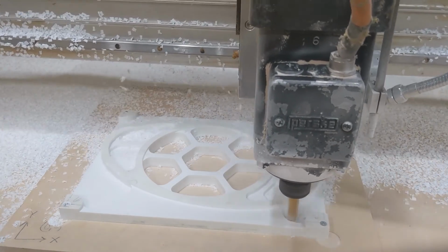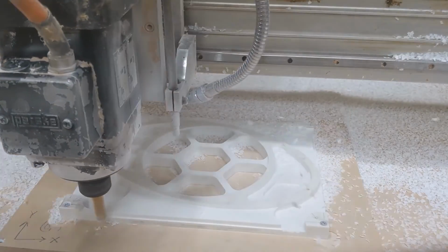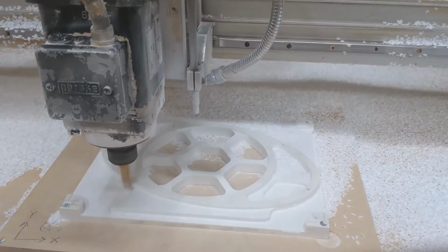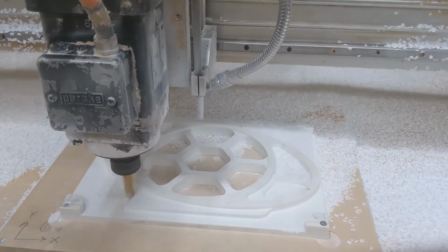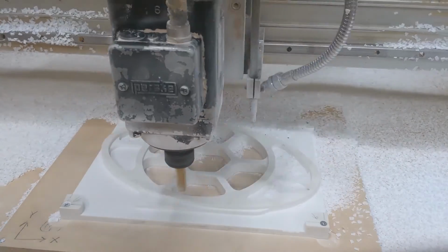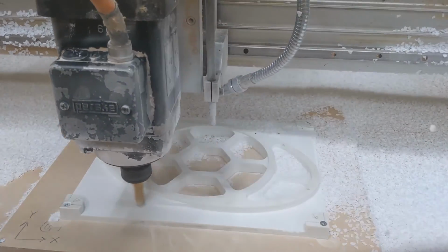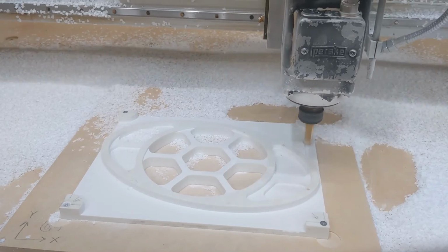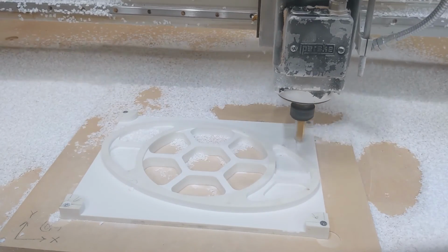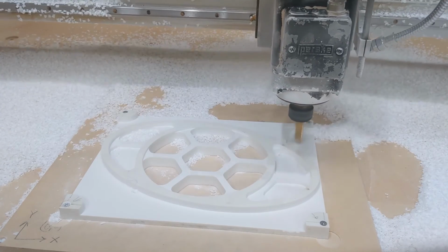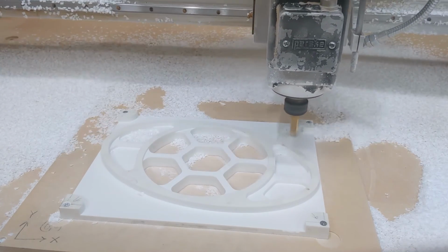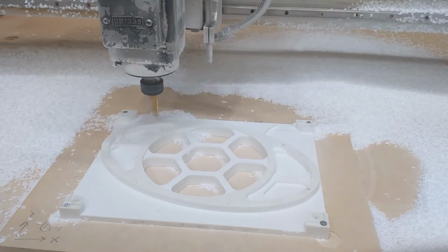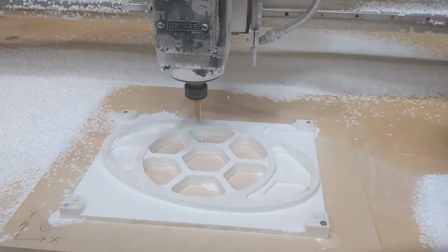1/3 cutter diameter for width of cut, and depth of cut really depends on the material, constraining how much material you're removing at a time. Maybe start at like a quarter of an inch and creep up to see if you're bogging the machine down. That's basically the limitation. And then the spindle speeds we don't have automated quite yet. I'm hoping to get to that next. But you can just, don't put it so high that it sounds like it's going to fly apart or the bearings are having problems. That's it.